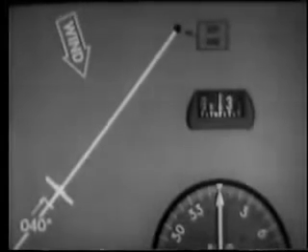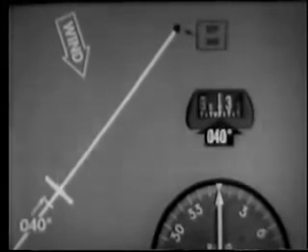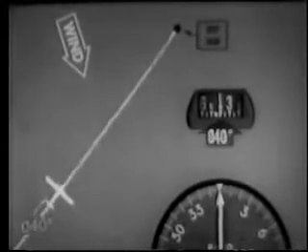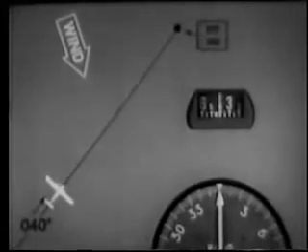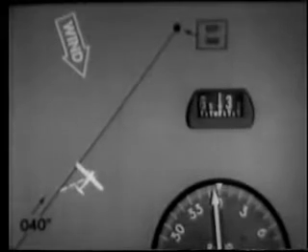We will use the tracking method. This involves finding the correct drift correction for wind by bracketing, so that we will maintain the desired track. The first step is to get on the desired track and on the heading of that track. Be careful to maintain the heading. Now watch the ADF needle for an indication of drift. Our needle is moving left, so our aircraft is drifting right. Now we must turn to a heading that will return us to the track. Normally 20 degrees is ample.